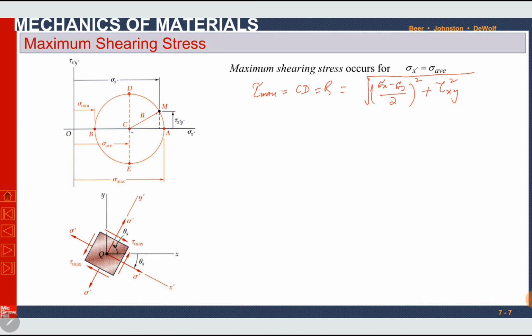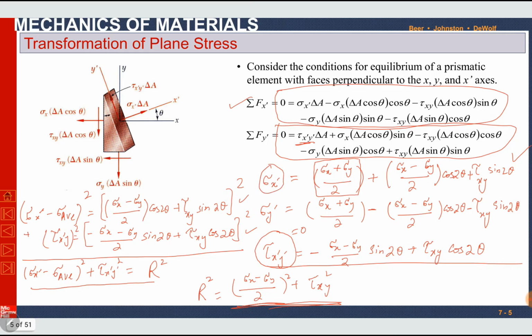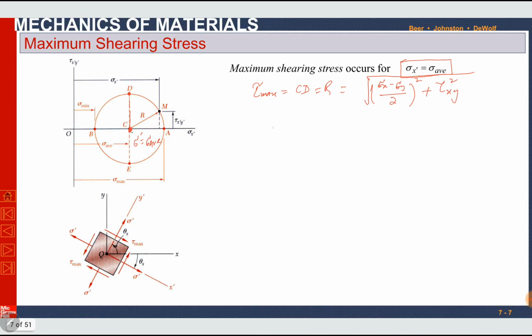Okay, before that, when shear stress is maximum at this point, the normal stress here is equal to sigma average. When shear stress is maximum, the normal stress will be average. So by putting normal stress equal to sigma average, sigma x plus sigma y divided by 2, in this expression, we can find the value of theta, and the value of tan 2 theta s, S is for shear plane, shear direction, becomes minus (sigma x minus sigma y) divided by 2 tau xy. Again the same convention, counterclockwise positive, clockwise negative.